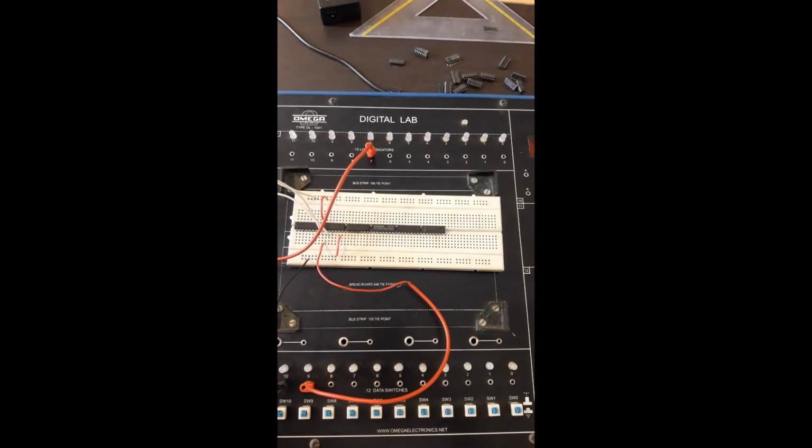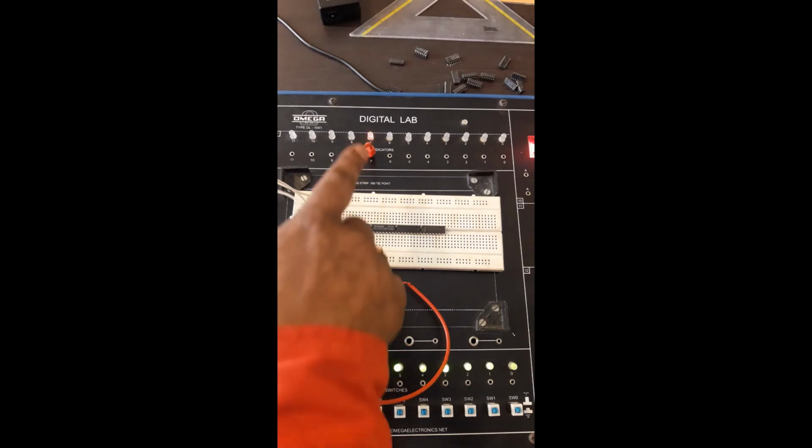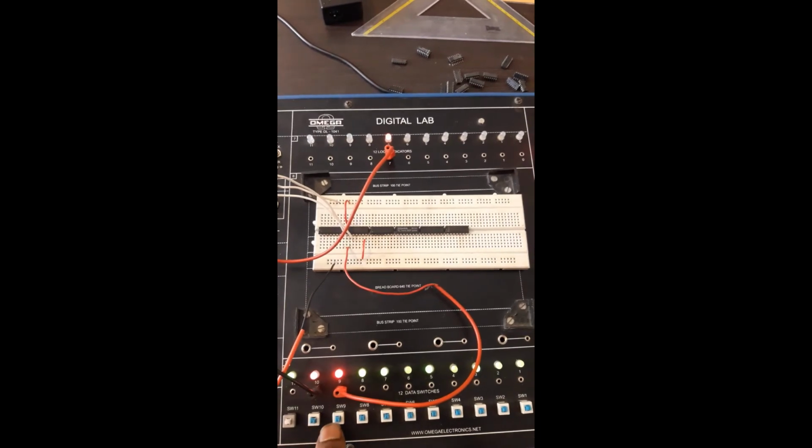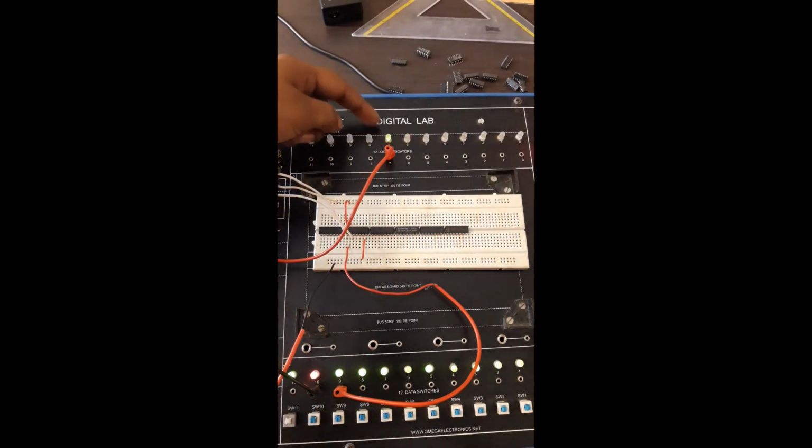Now if we switch on the device, you can see when it is 0 0, it should be 0, and when it is 1 1, it should be 1. Now it's working properly. So everything is 0. We will work with these two terminals, these are the inputs for this case. Initially it was 0 0, so the output is 0. Then we will give 0 1, and the output will be 0 again. Then 1 0, the output will be 0, and then 1 1, the output will be high.